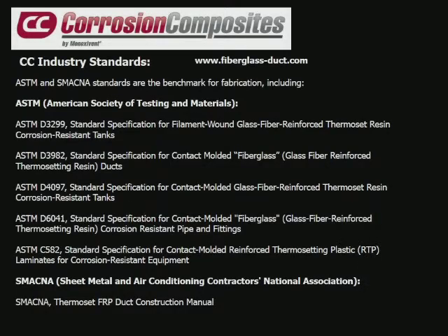What we're looking at here are the industry standards. The corrosion industry really got its start in the 50s. Some of the fiberglass tanks that were built back then are still in service from the 1950s. The ASTM standards all arose from an old standard called PS 1569, which some of you may have heard of. The ASTM standards cover pipe, tanks, duct, and your ASTM C582 is the critical one.